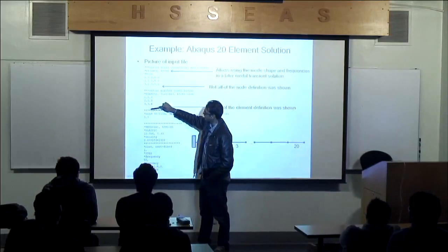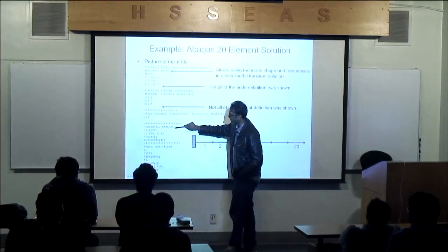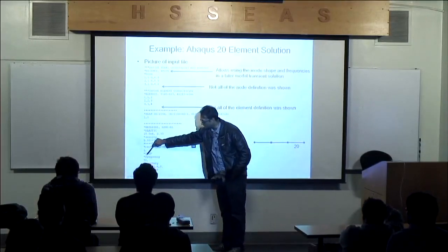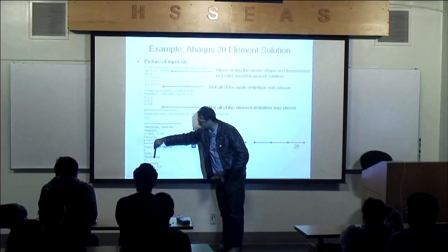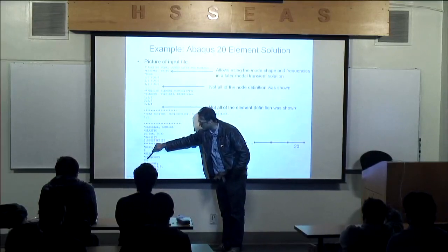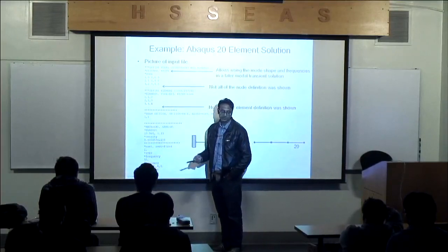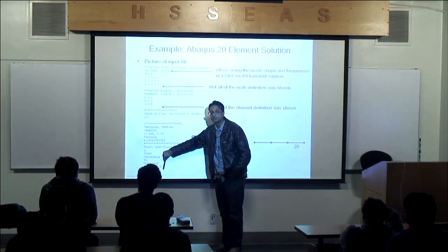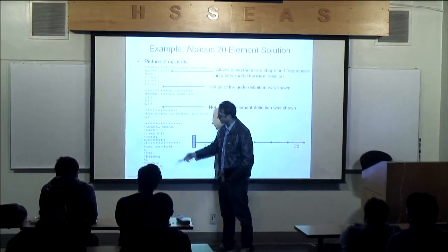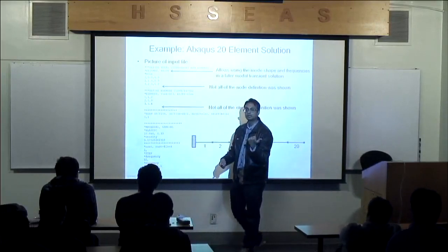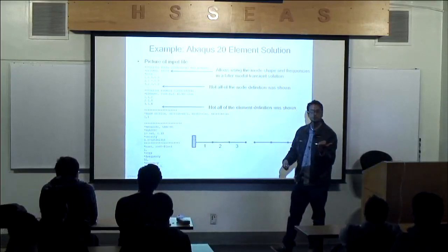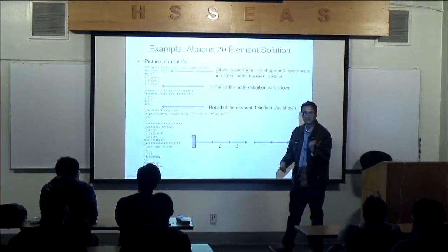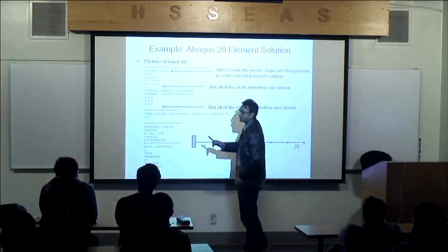Element definition, beam section the same as before, material, elastic, density, and then you have the step, and it's as simple as putting a frequency command, star frequency, and I asked for 50 modes. In reality, I should have asked for 40. I have boundary conditions fixed on the left-hand side, and that's it. That'll be enough, and it will give you the modes. You see how simple that is? I cannot make it more simple, because it's simple.